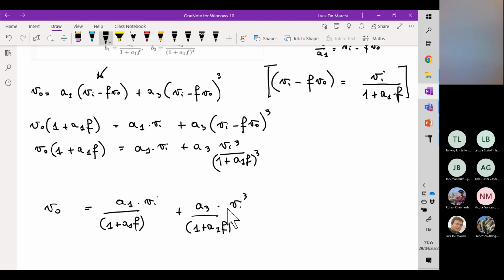We have to look at the phase at this point, and the phase is here. Since we have a lot of phase margin, because the distance between this point and the minus 180-degree curve is very large, then we do have stability. We can do the same by looking at the so-called gain margin, but typically, again, I would recommend to focus on the phase margin.